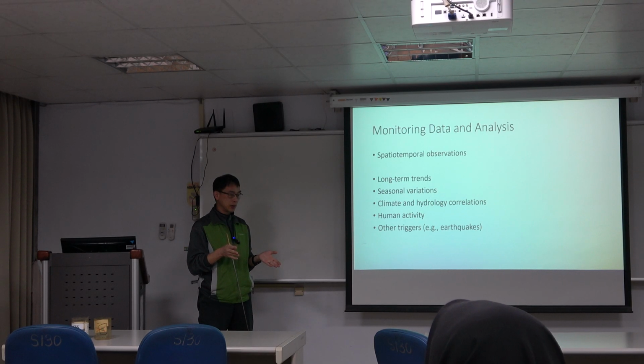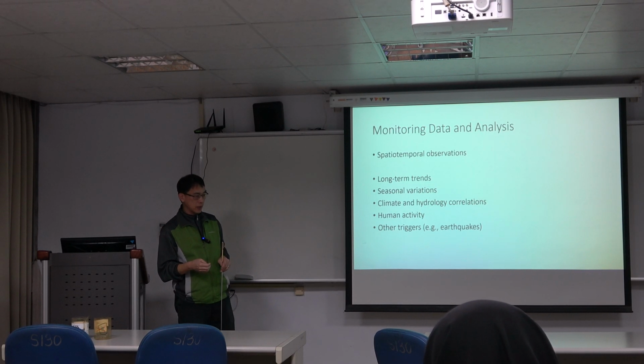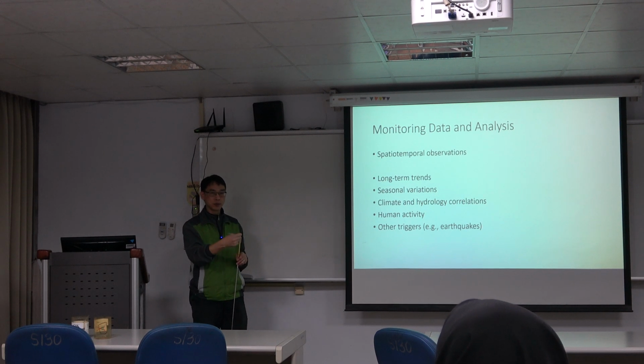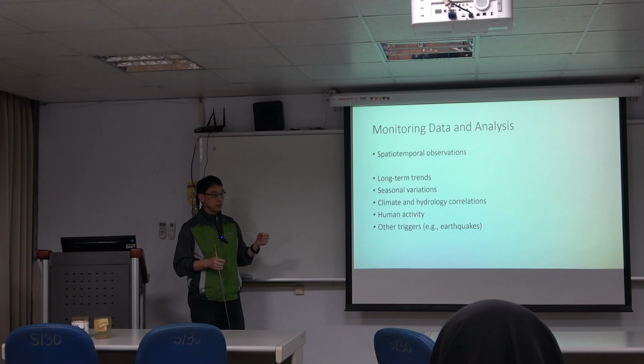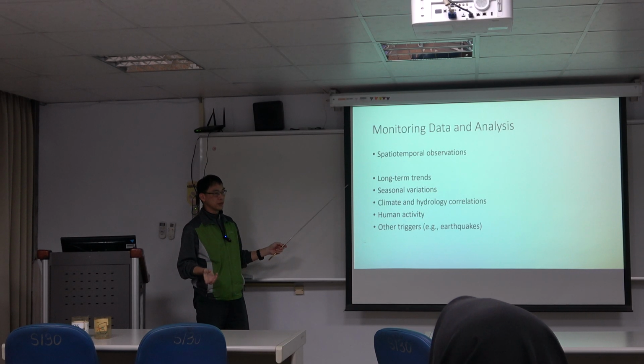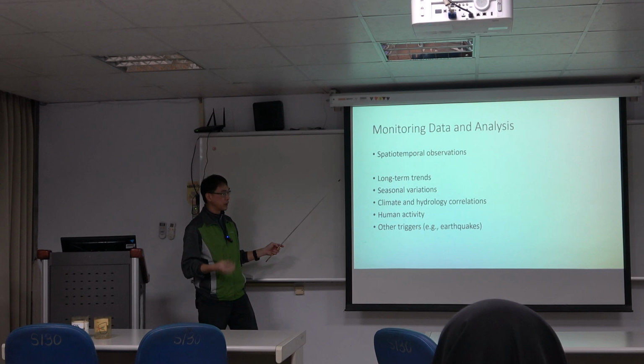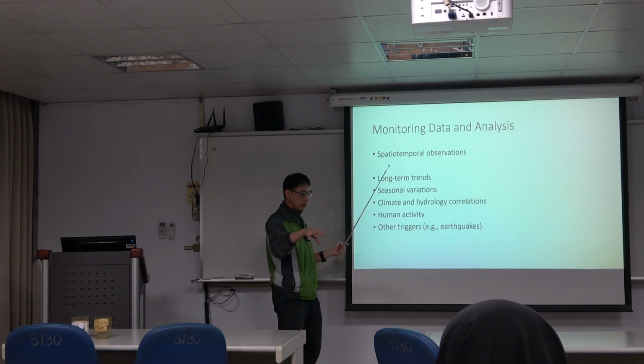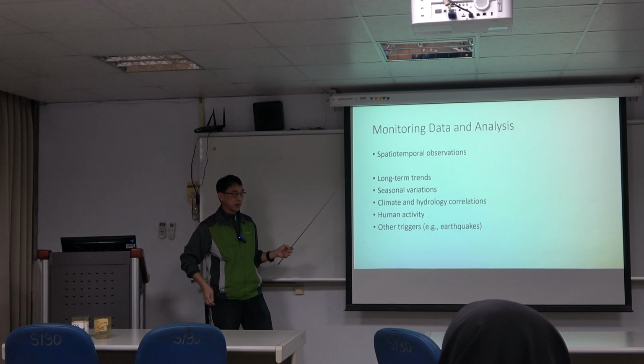But chemical analysis commonly is not easy to do with continuous measurements. You might take a sample every month, every week, or every season, and take it back to do the analysis. Although some devices right now are able to make continuous measurements in situ, it's not very popular. Commonly, the continuous measurement will be the water level or parameters. So we put a device in situ to measure the water levels, and we will be able to obtain the overall water level record.